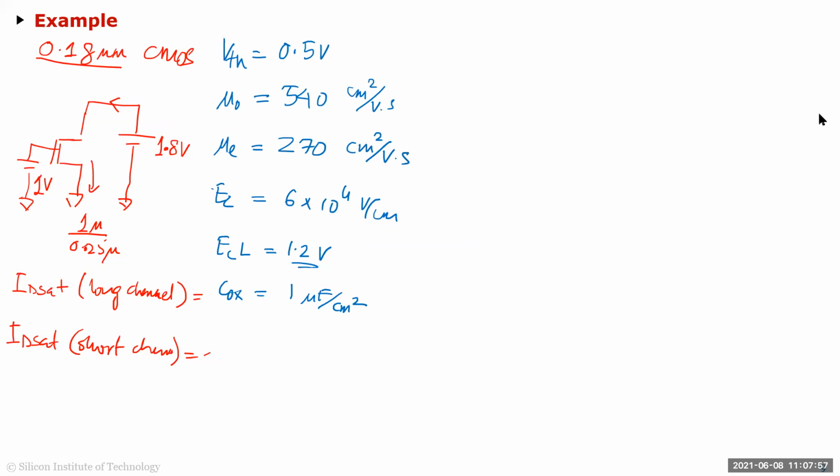Okay, I'm going to go one by one. You guys have to answer now. Srishti Rani, what's the condition for saturation? What condition has to be made for saturation? Sir, VDS should be less than VGS minus VT for saturation, and for linear, sir, VDS should be greater than VGS minus VT. Okay, so why didn't you come and just say that? Okay, how about Pragya Rath? What do you think is the condition for saturation? Okay, thanks, Srishti. At least you gave some answer. Thank you, sir.